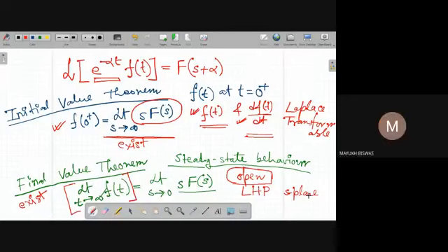Sorry, excluding the imaginary axis. Right. What happens if the poles are on the imaginary axis? So the system may be marginally stable or maybe unstable. No, it will be marginally stable, and the result may be unstable also if the roots are multiple roots on the imaginary axis.